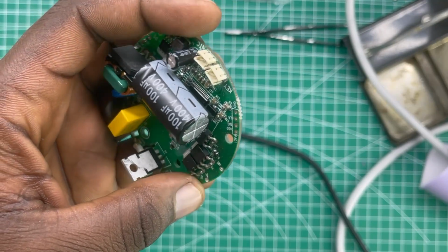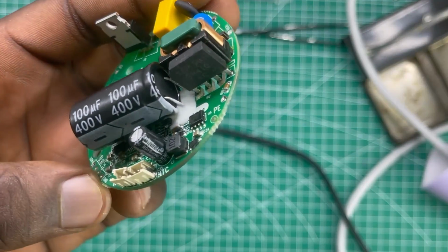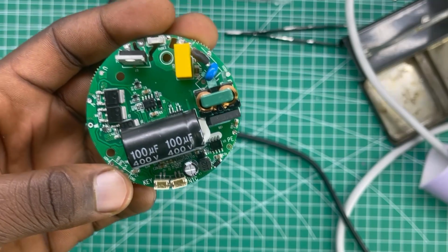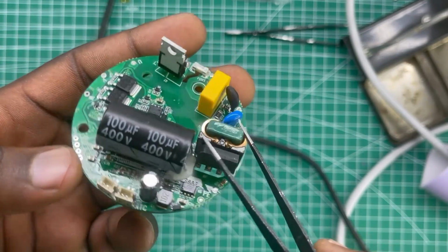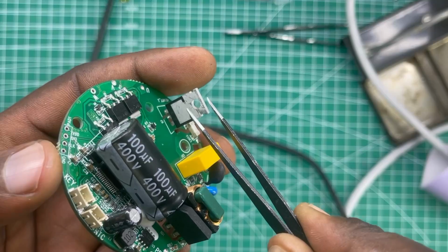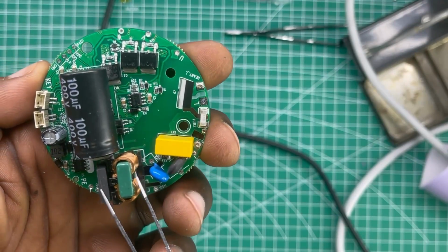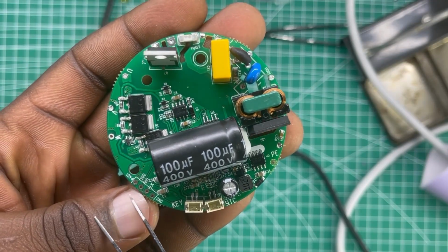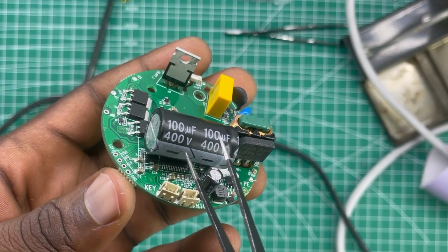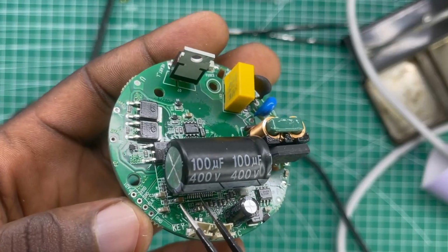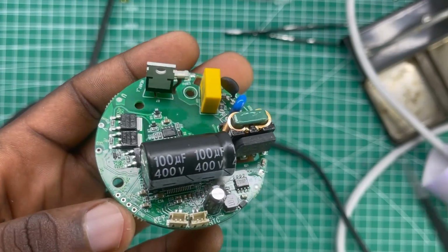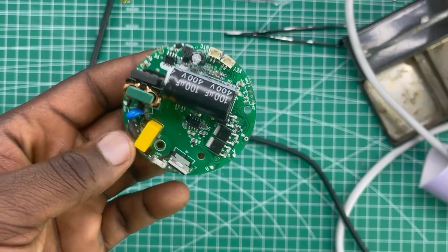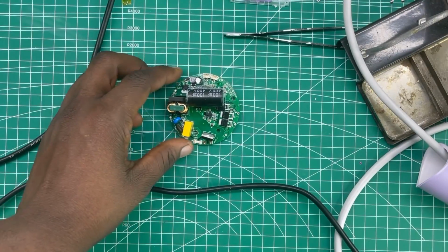Okay, so now we're going to look at the PCB, and we're going to be looking at the main components. So as you can see, the PCB has the standard main components you would expect. A capacitor, this is a thyristor, it's for controlling temperature of the coil, and these inductors and capacitors, they are for voltage regulation. On the left, you can see the MOS drivers, the 3 MOS drivers, and right underneath this capacitor, we are going to see the MCU.